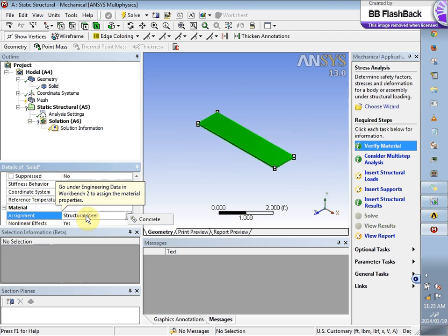So it is fine, we are happy with this structural steel. So for all materials, if there is a steel plate, a concrete plate, all other things, we'll keep on clicking them and keep on selecting new materials for that. If you want to go up to the nonlinear analysis range, you can set nonlinear effects there, but let's not choose it now. Let's leave it to the wizard. Whatever the wizard thinks is best to be defined, we'll keep on checking it.